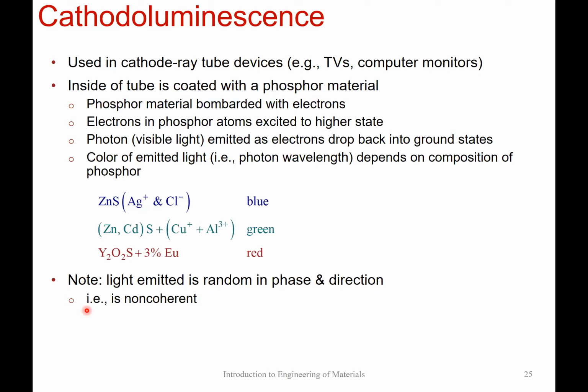And that's also been quite useful as a characterization technique to understand how semiconductor devices have been fabricated. Let's say some sort of semiconductor layered device has been fabricated; in terms of its composition and the different layers that have been constructed, you can characterize how uniform and how crystalline those layers have been, and also the composition, by using cathodoluminescence.